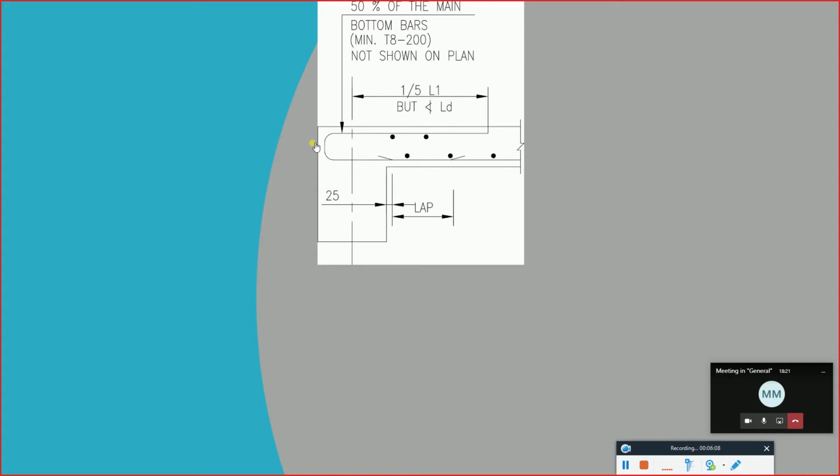Okay, in the end support case, whether it's a simply supported slab or a discontinuous slab, you should know that the bending moment is parabolic. It's parabolic, and at the end where there is a discontinuous joint or a simply supported joint, the bending moment is zero. But if the bending moment is zero, normally we don't have steel because the moment is zero.